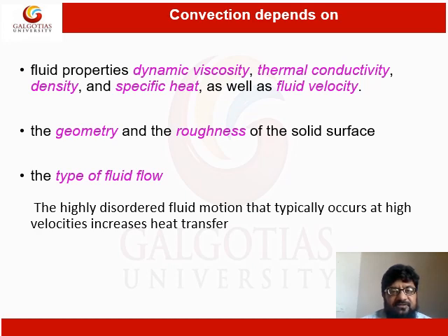The rate of convection heat transfer also depends upon the type of fluid flow. A turbulent flow will typically increase the rate of heat transfer because the highly disordered motion of the fluid particles enhances the rate of heat transfer from the solid heated surface to the cooler fluid.